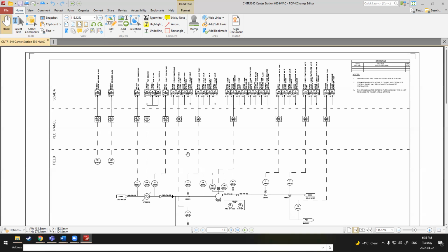But beyond that, you have to put all the terminal blocks inside of your panel. You have to design your back plane. You have to pick a size for your panel. You've got to try to fill it all up. If the back plane's too full, you have to pick a bigger panel and redesign. Yeah, this is the beginnings of the design process for a panel, then software, then entire plants.